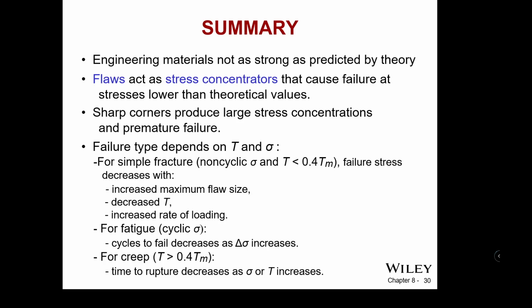That sharp corner introduction produces large stress concentrators and creates the condition for premature failures, especially in terms of shear. Not always so much in tension, but almost always in shear. They become very, very vulnerable in shear for stress concentrators.